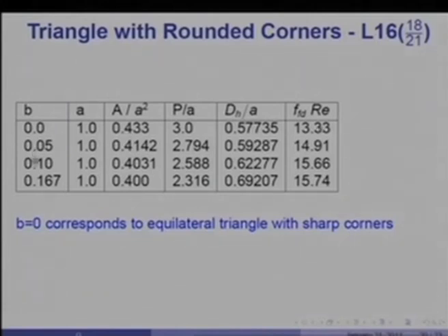But as the rounding radius increases, you see that the friction factor versus Reynolds number seems to increase, but based on hydraulic diameter, where the hydraulic diameter itself goes on increasing with the rounding radius. Let us take yet another problem.